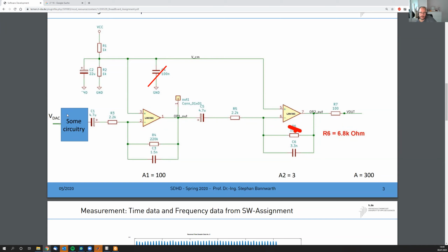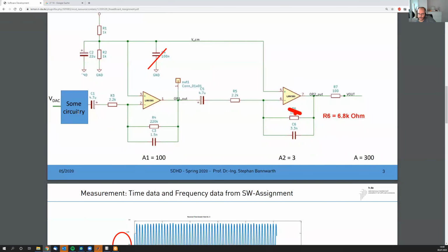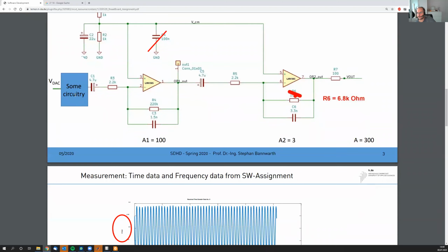And at least Mr. Hubrich said that, I have not verified that, said the inner resistance is something like 4K. Okay, so which means if you connect your circuitry here, your voltage divider, you have to make sure that the inner resistance will not go too much into that whole thing, right?